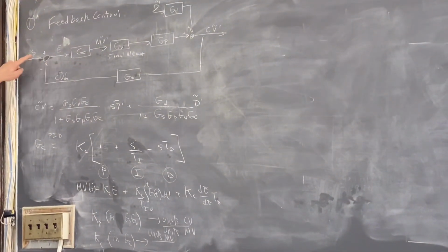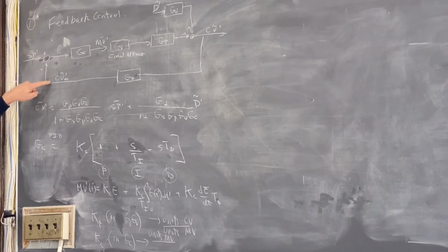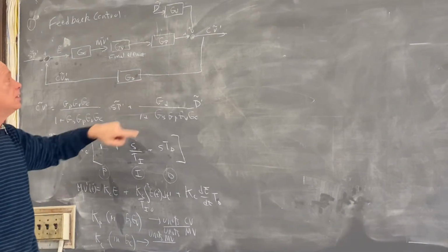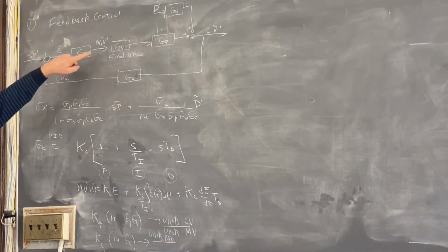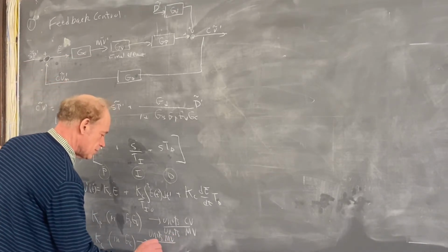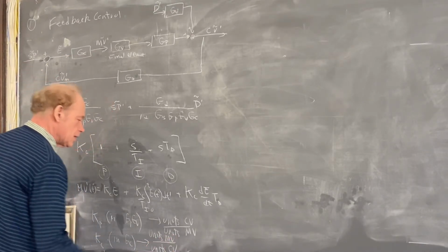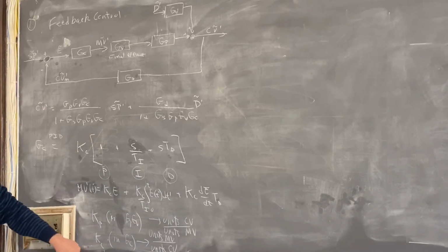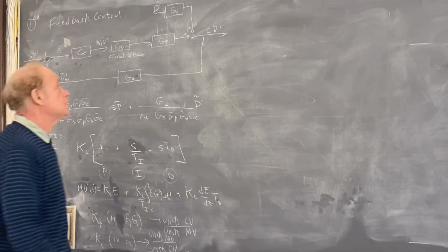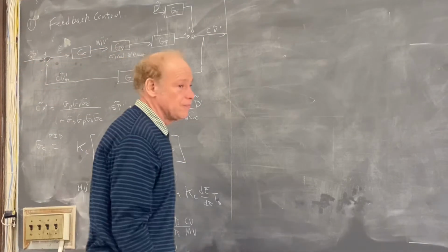Well, the error is the difference between the set point and the measured control variable. And the control variable measured presumably has the same units as the control variable. So it has units of the manipulated variable over the control variable. So KP and KC have inverse units. So if I multiply them together, I get something that's dimensionless. So that's something to recall.